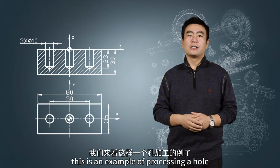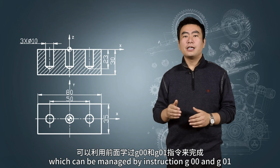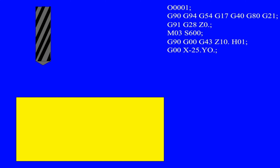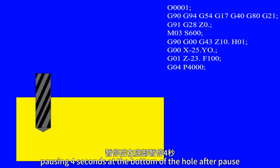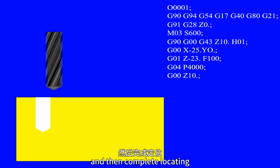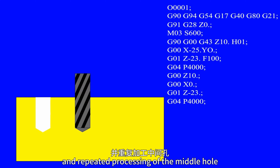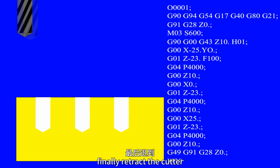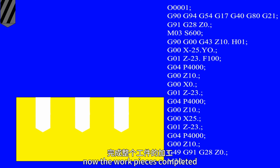This is an example of processing a hole, which can be managed by instructions G00 and G01. First, control the machine tool to finish the setting of initialization. Then, control the cutting tool to locate in the Z direction. Subsequently, control it to locate on the XY surface of the first hole. Perform cutting to a depth of 23 mm in the first hole, pausing 4 seconds at the bottom of the hole. After the pause, lift the cutter out of the bottom of the hole, and then complete locating and repeated processing of the middle hole and the right hole. Finally, retract the cutter, and then the program ends. Now, the workpiece is completed.